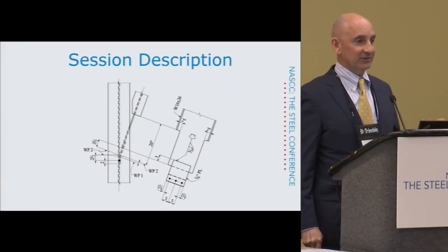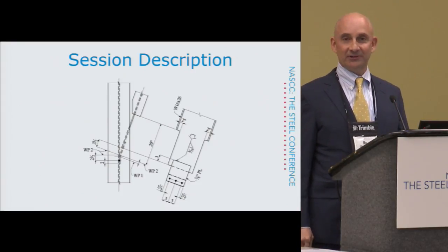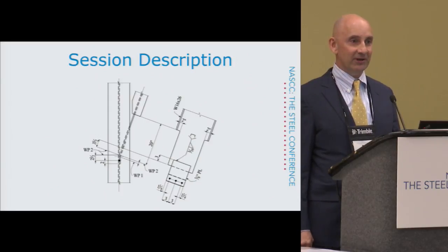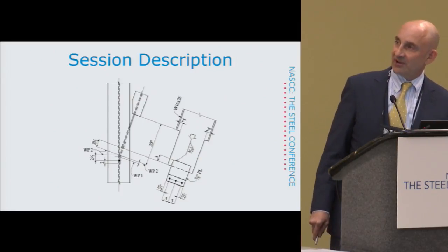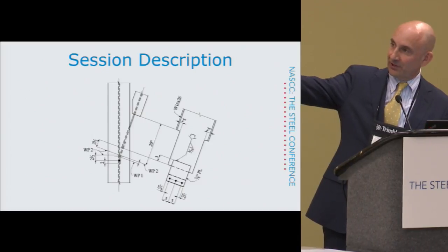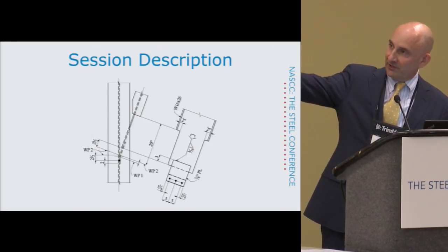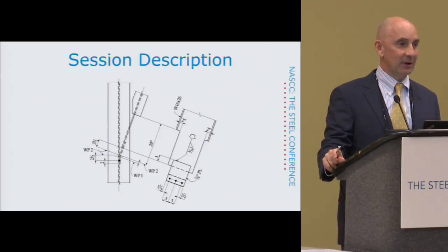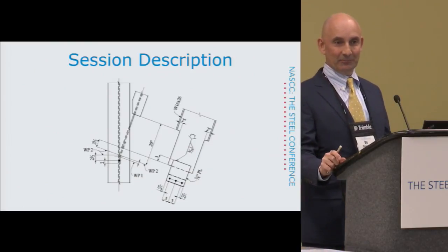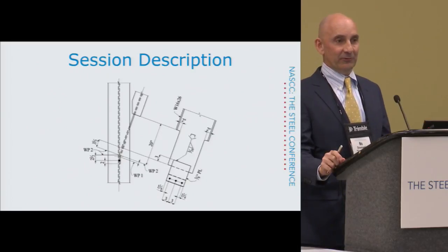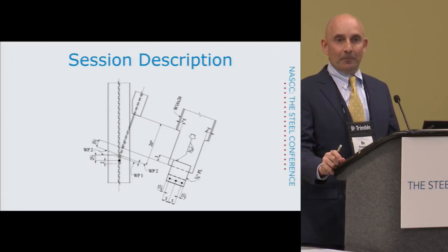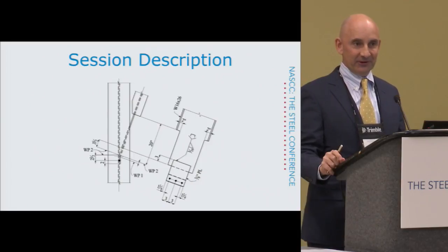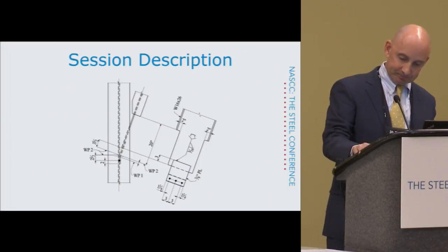So you've got a W16x26, which first of all has a thin web. I believe it's right around 1/4 of an inch. And then due to this tight skew, you end up with roughly a 20-inch cope, from the work point to the face of the cope. And then you're framing to a member of the same nominal depth, so you end up with a double cope. So all of these things put together means that you're going to fail in buckling rather than yielding on this beam, on this cope.